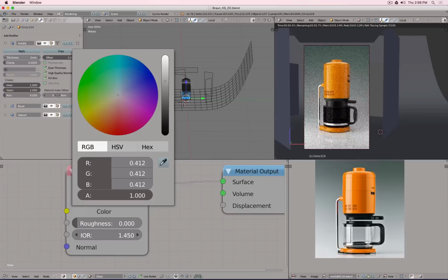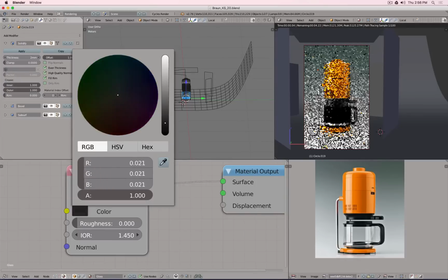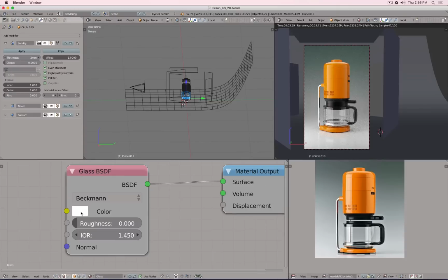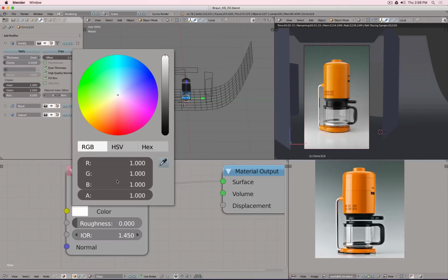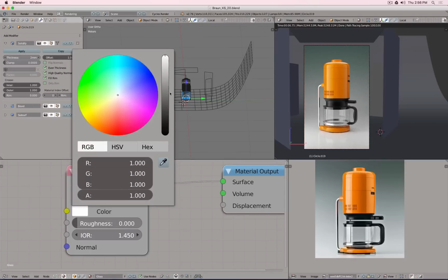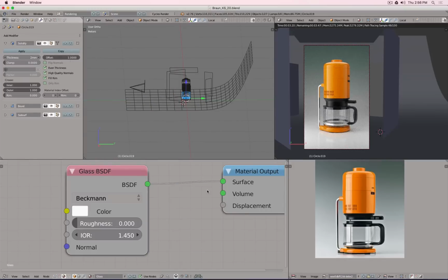So obviously the darker I make the glass, the less clear the reflection will be. I want to have nice clear reflections. So in that case, I need to have RGB set to 1, and now you can see nicely through that object. However, you notice that there is a little bit of darkness, so this backdrop here behind the glass should look a tick darker. So this can't be 100% white. Maybe just a little bit there.